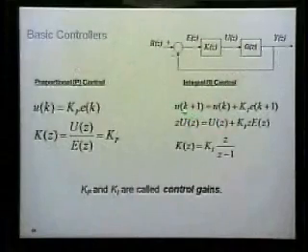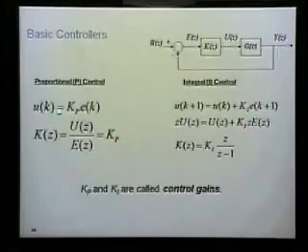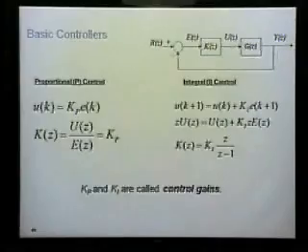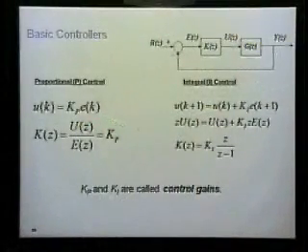The integral controller as well, you can see what happens here. The intuition behind the integral controller is that the value of the control, like max users at time k plus 1, is what you had before plus some delta having to do with the control error. The constant there is k sub I for the integral controller, and k sub p just looks at the control error and scales it. One intuition is that if your control error is 0, the system's doing fine, and you shouldn't change anything.